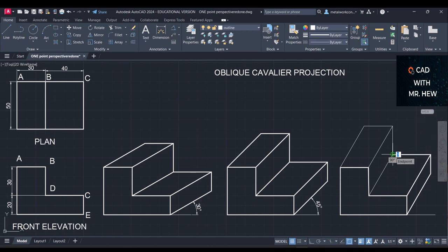And then you go again. If you're using a T-square and set square, the lines that I drew before would be 4H lines, and the ones I'm drawing now are outlines using a 2H or 3H pencil. Is that clear? Good. So we're going to come there, there, there, there. Good. And this is the third way in which you can draw the oblique cavalier projection, right?